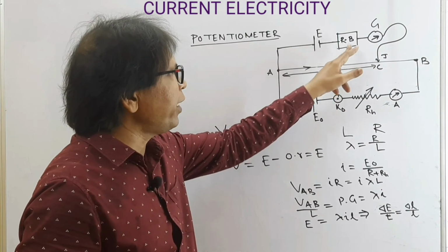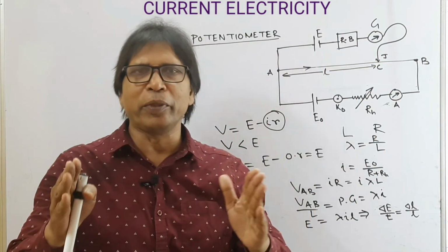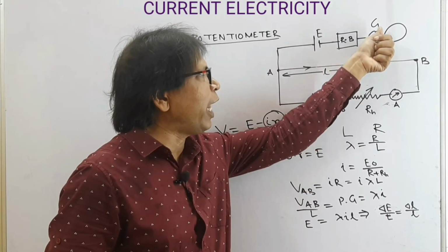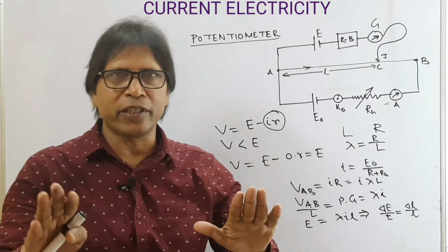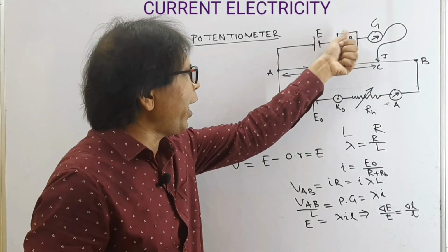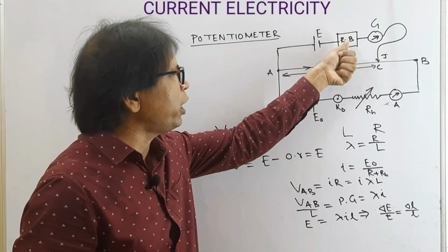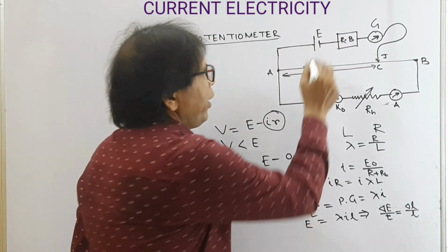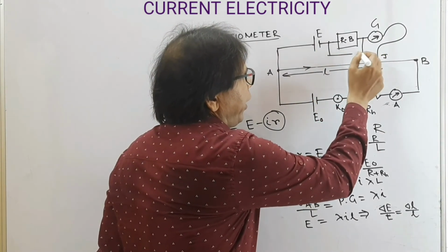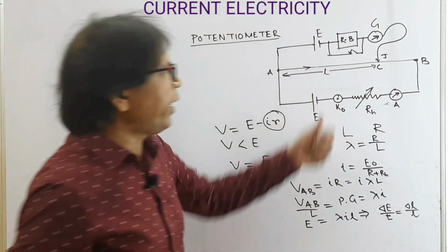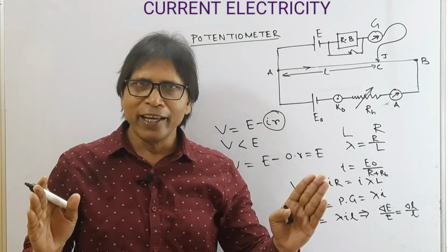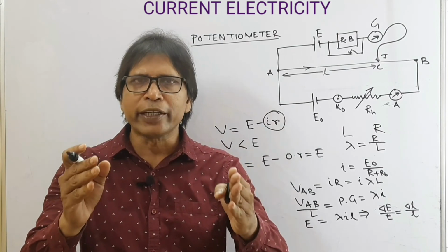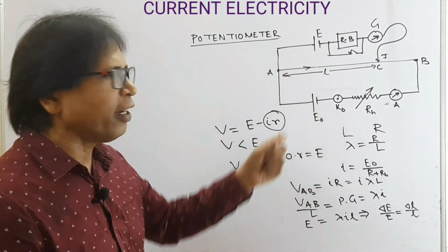A resistance box is the safety device for the galvanometer. If high current passes through the galvanometer, then the galvanometer may get damaged. So to protect it, a high resistance is connected in series with the galvanometer. Near the null point, a short circuit key is added here to get the null point. Now, an EMF in the order of microvolt can be measured with the potentiometer.